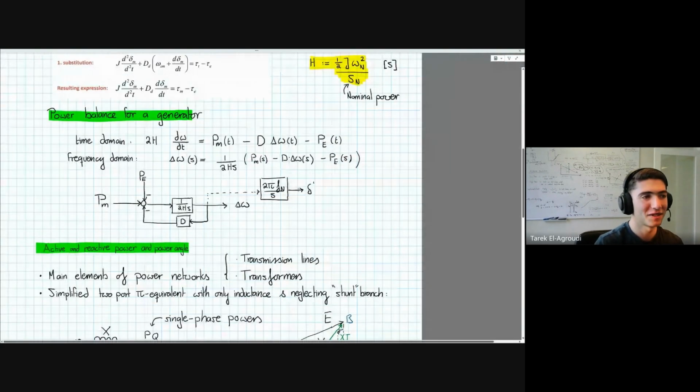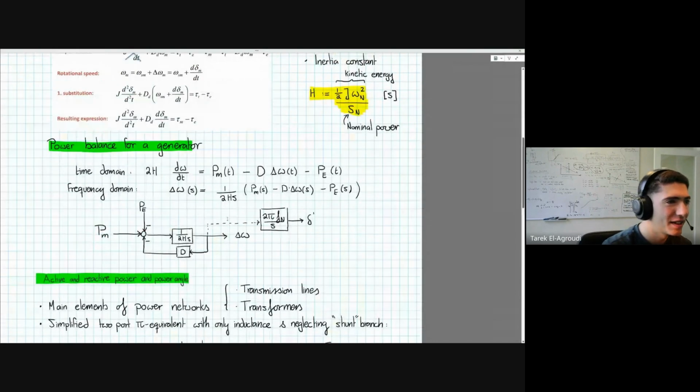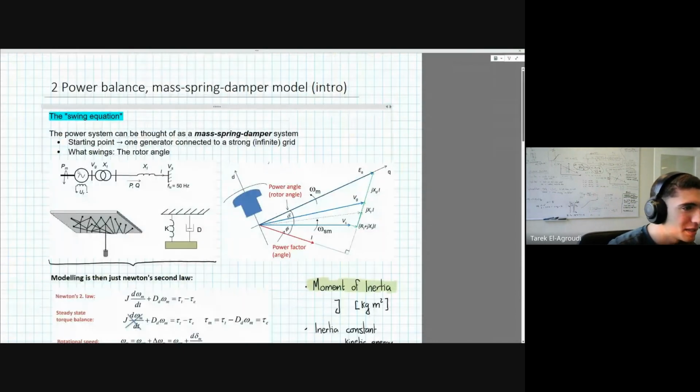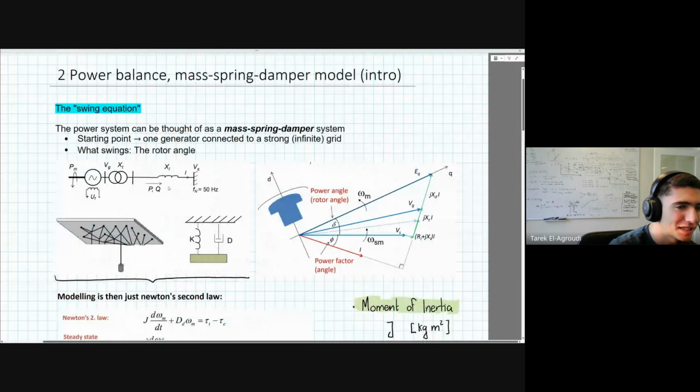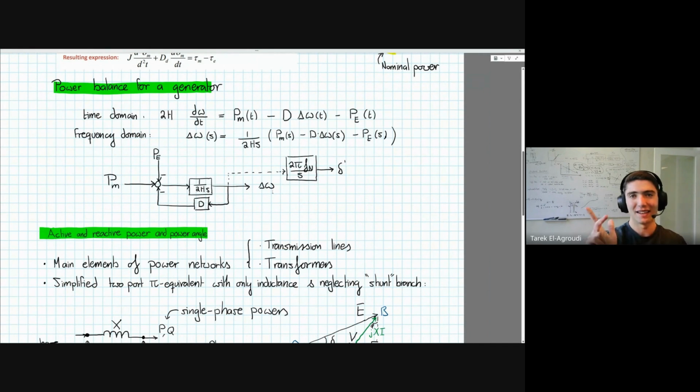It's important to understand, because seeing as it's just the integral of the speed deviation, I may actually break down a bit, because I'll reiterate what this delta omega here is. This is not just the grid frequency. This is the deviation from the nominal grid frequency. So it's like some error coordinate. But the integral of this is this power angle, and since it's the integral of some speeds, you need to sort of initialize it somewhere. So which angle is it, sort of?